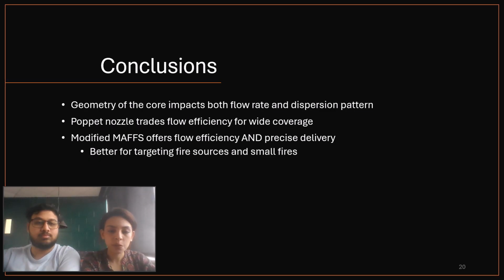So concluding this presentation project, the geometry of the nozzle impacts both flow rate and dispersion pattern. The poppet nozzle trades flow efficiency for wide coverage. Modified MAFs offers flow efficiency and precision delivery for targeting fire sources and small fires.